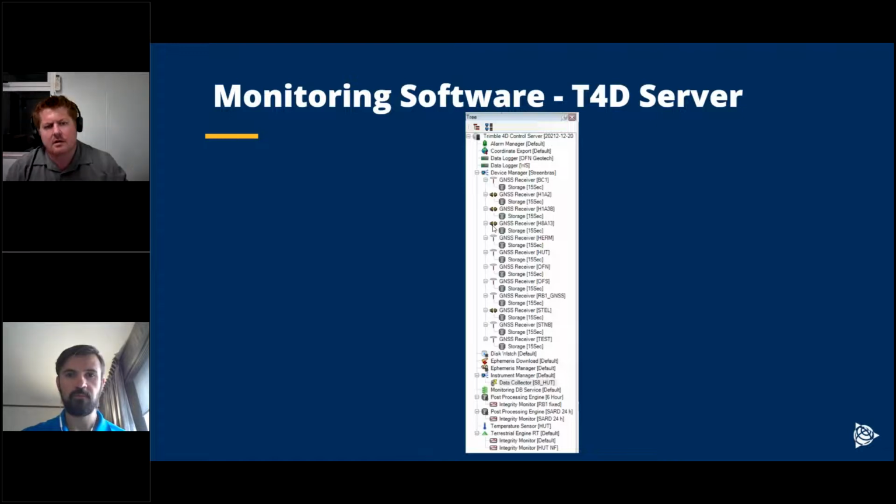TrigNet operates about 70 CORS stations around South Africa. So we've used a couple of the closest ones. Incidentally, one of them is actually at Steenbras Dam, so it's quite close. And then we use, I think, two or three other ones which are a bit further away. You can also see there are quite a number of stations at the moment disconnected. That's just at the Aquifer project, where they're busy working on the station, so they currently don't have any power.